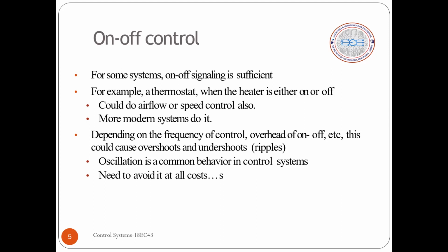Similarly, if the temperature is below the set point, it may turn on the heater, or if the temperature is going above, it may turn off the heater. So it is hardly any job here. The controller's job is only to turn on and turn off. Only two jobs it will be doing. So a very simple controller it is.